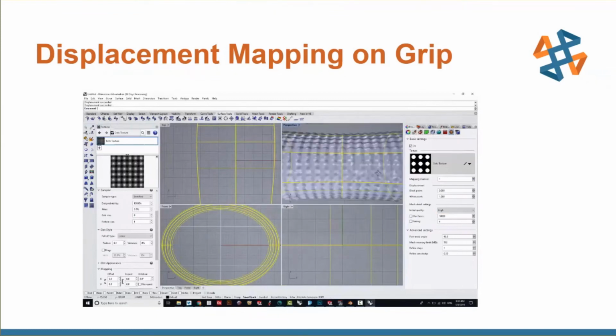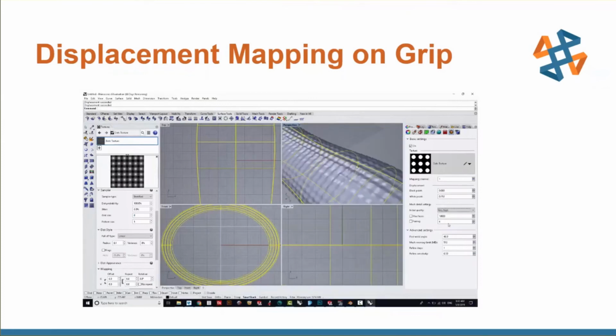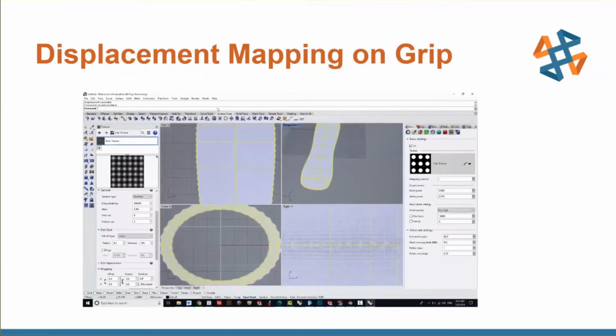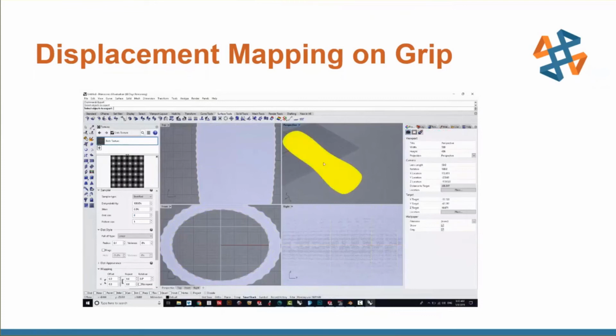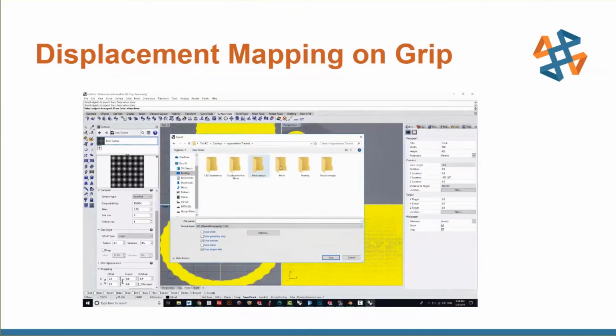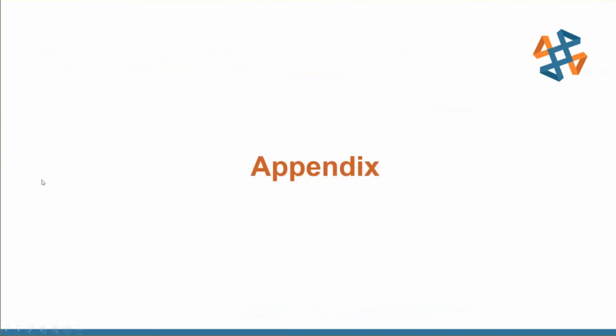And my last step after I apply this is to triangulate my model and export that mesh. And you can see it's a very high polygon mesh. So keep in mind that when you do this workflow that you will be doing data intensive processes. So I would recommend doing it on a system that has a good amount of RAM, which is really key in doing some of this. And so I saved that out. So that's kind of the bulk of it.